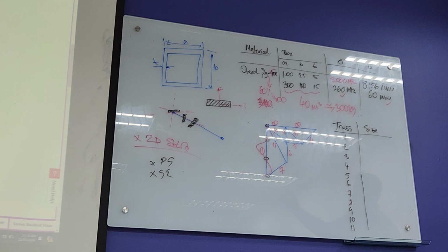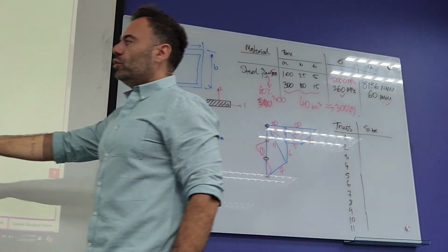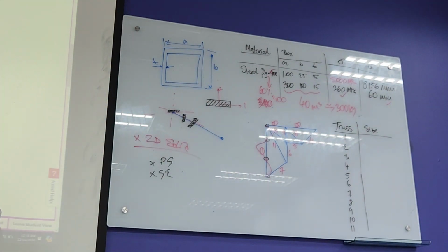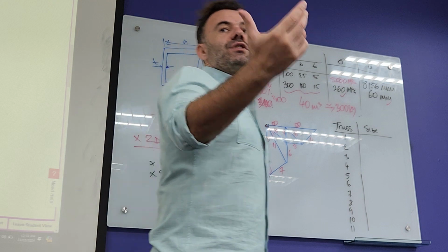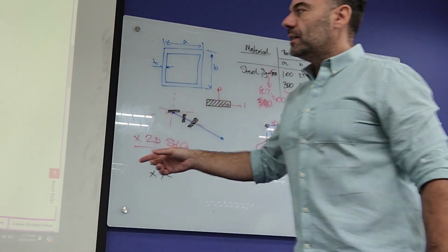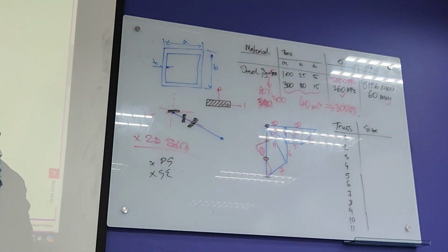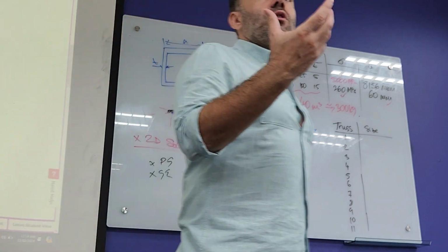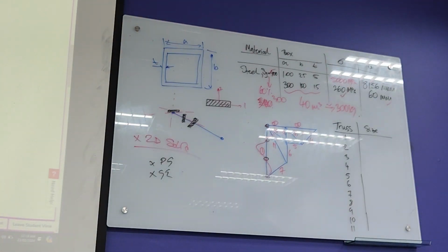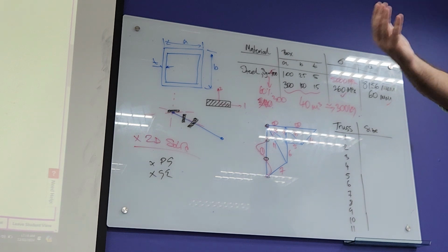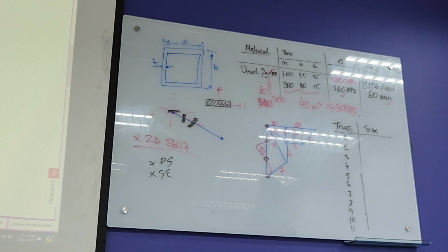Not everything can be plane stress, not everything can be plane strain. Yeah? And you have to differentiate between the two. So that's why I didn't say here use plane stress or use plane strain. It's like use 2D solid and listed the options. So you have to choose the correct, appropriate modeling type. If you want, you can choose the other one and see what the difference is.